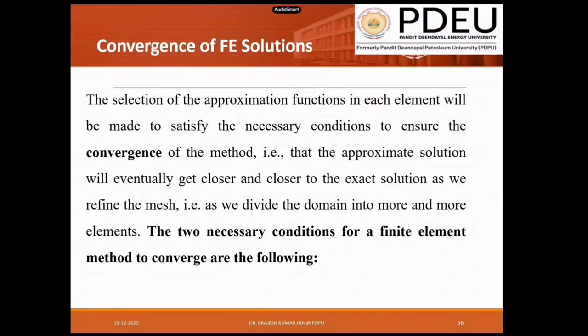Okay, so in the last few minutes, I will talk about the convergence of the method. Approximation of the element is very well defined according to the finite element method, but your solution should be converged. The convergence of the solution is very important, so that it will match the exact solution or be close to the exact solution. So mesh refinement can be done. One way is mesh refinement. Some necessary conditions for the FEM method to converge are as follows.